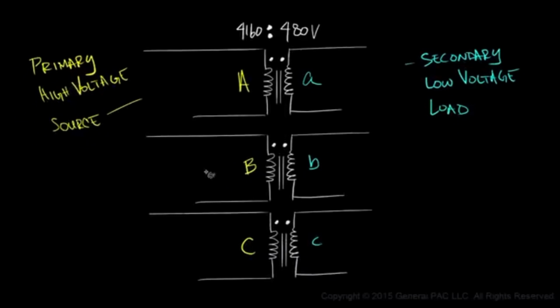So we can start to connect the secondary windings. First connect the A to B and B to C together, and also they have neutral wires. This is the wye grounded transformer connection, which has different characteristics.